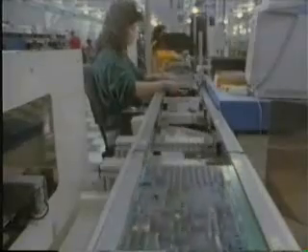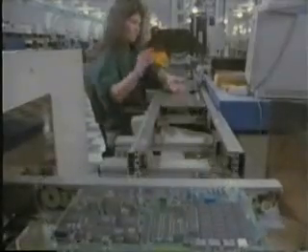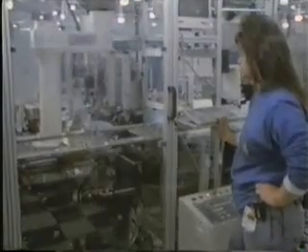This twin station temporarily glues tiny devices to the bottom of the board until they can be soldered later in the process. The circuit board is again subjected to infrared reflow to harden the glue and then flips back to the top side. The other way of placing parts on the board is the through-hole assembly process. Here, electronic components with wire leads are inserted through holes in the circuit board.